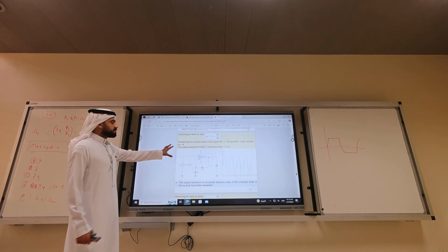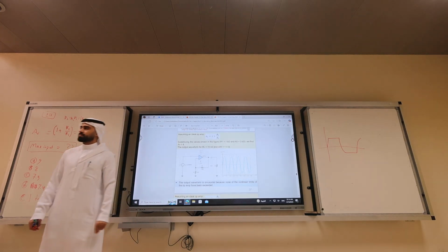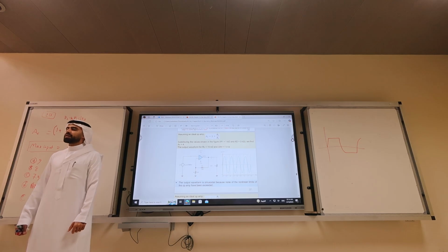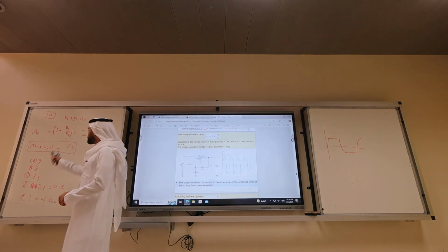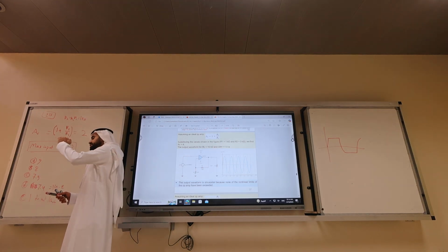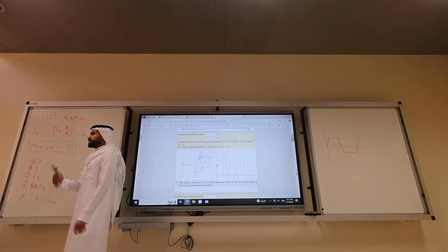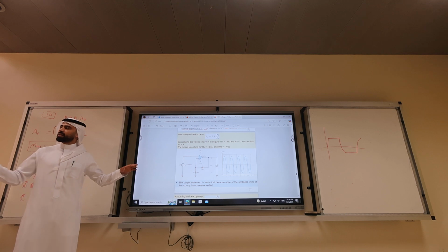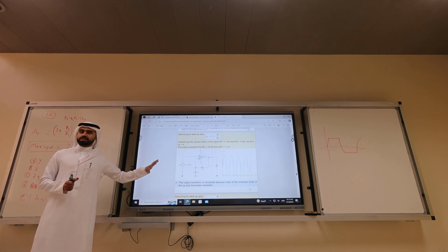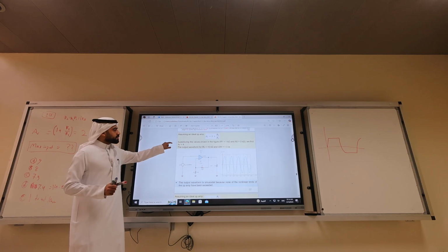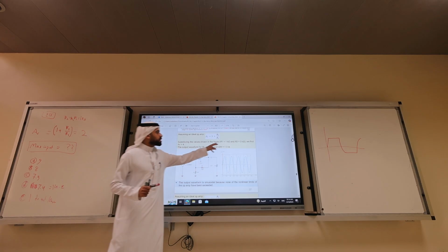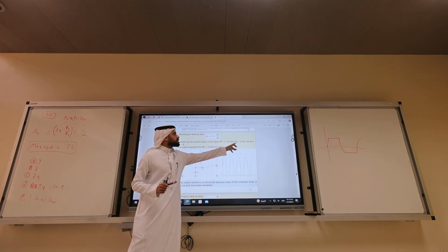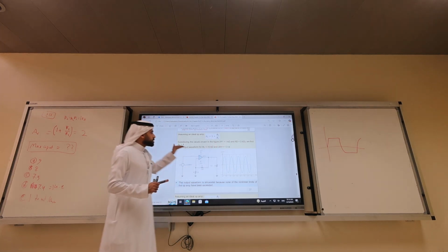This slide is similar. Non-linear limitations means it's not linear with the input. For example, you don't get the clipping linearly changing. You get it suddenly, non-linear. Get it? There are other factors, for example, the frequency rate of the change will show it, but it's not required. This slide is very similar, but this is another idea, you have to get R1 and R2. You have to calculate the gain. 1 plus 3 over 1 is what? 4. So the gain is 4.